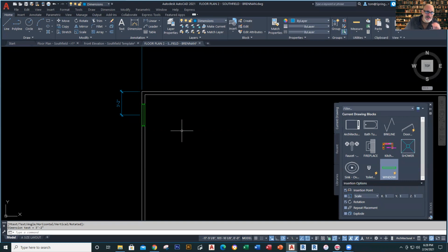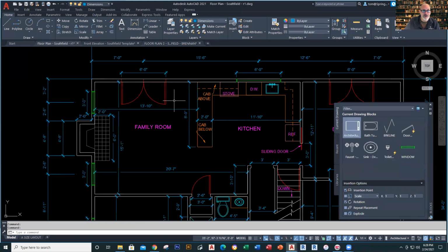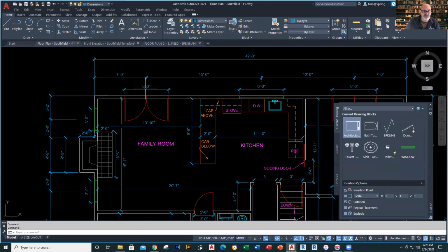So that's how we go ahead and put in one of the doors. Now, let's take a look at how we do the windows. That's a window. Now over here, I've got these doors, which are 6 feet, okay? That means each one's going to be 3 feet wide. And the center is at 7 feet. The double door is at 7 feet, centered, okay?